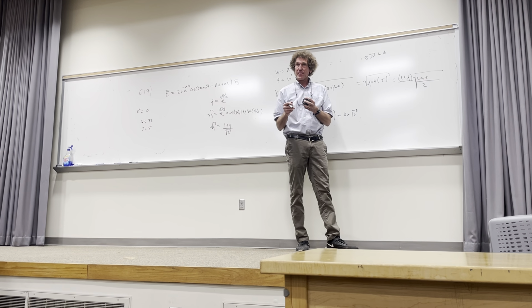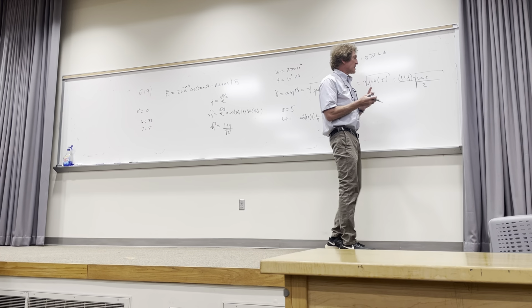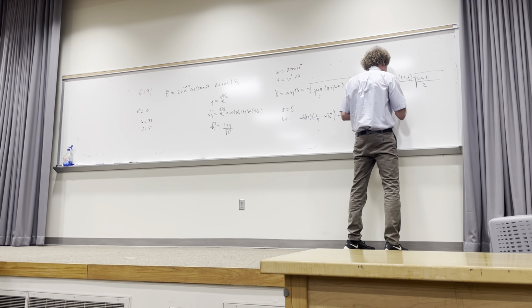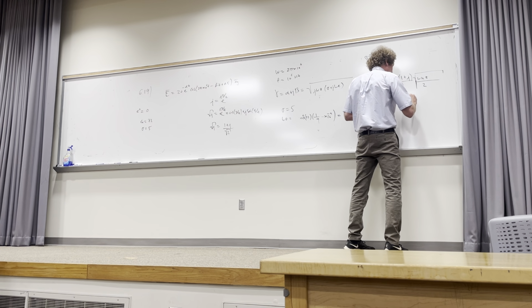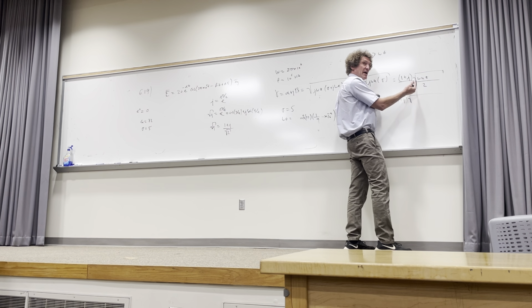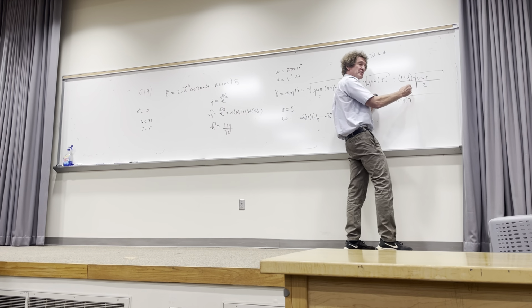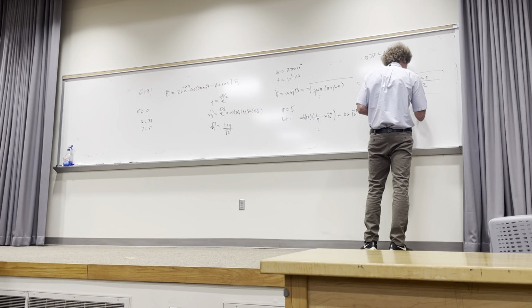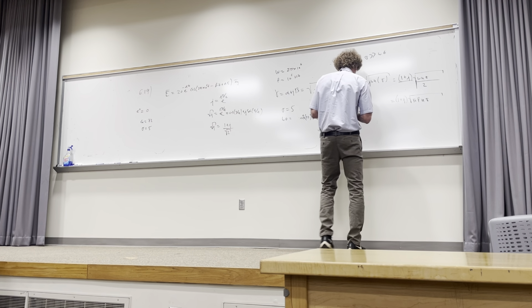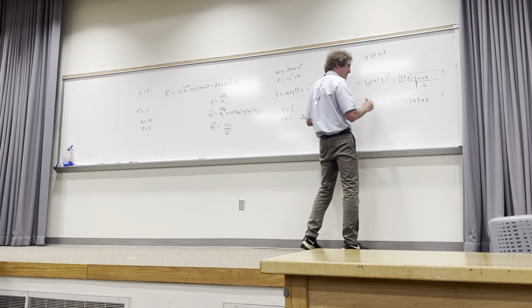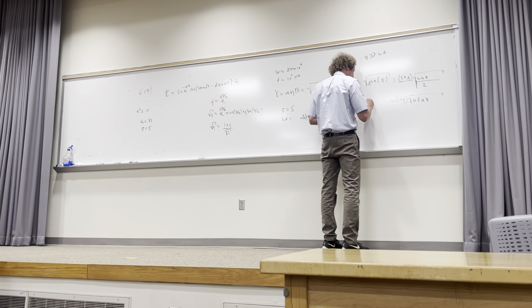Y'all follow me? All right, what is omega? If I take a look at this, isn't this 1 plus j? And then if I take a look at this, it's square root, well, omega is 2 pi f, isn't it? Can you all see that? So if you put in 2 pi f by 2, you get pi f and then mu sigma. And what you'll find out is that is alpha plus j beta, or gamma, for a good conductor.